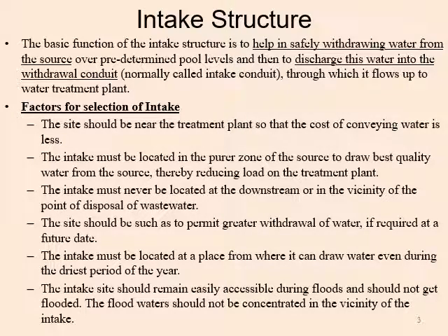The intake site should remain easily accessible during floods and should not get flooded. It means the intake structure, a concrete structure or masonry structure, nowadays a concrete structure is generally constructed, should remain easily accessible also in flood conditions, and it should not get flooded, means it should not be buried under the flood water.